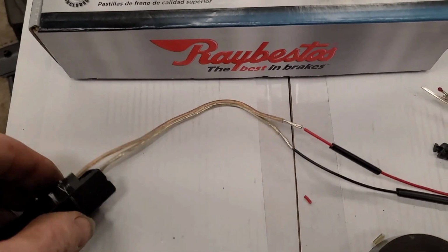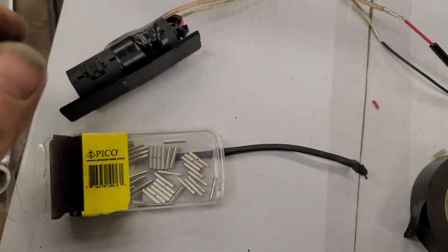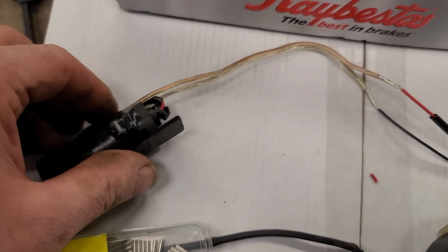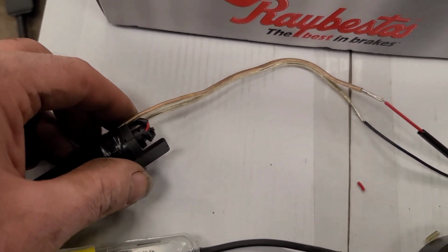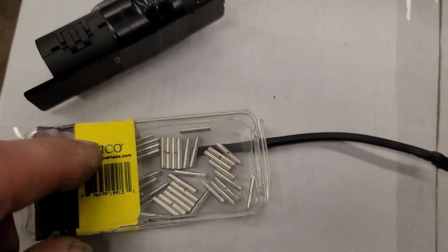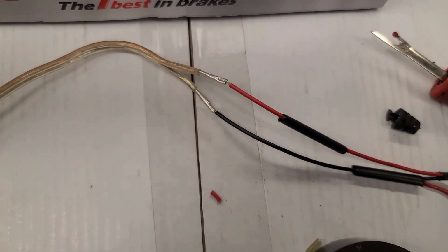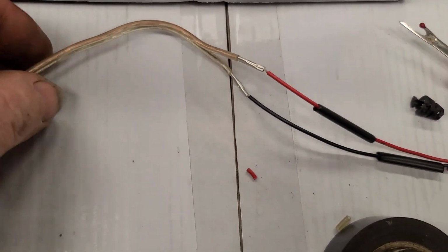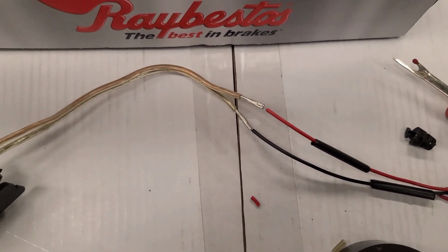So I decided I had nothing to really lose except a few minutes here to splice some wires. So I managed to cut this off, and I made the splice and folded it up so that it hopefully won't bend there. And I used some speaker wire to attach it in these uninsulated butt sleeves, and a little bit of heat shrink, extend the wires, make the joint somewhere else so that this part of the wire will bend with the seat movement, and we'll put it back together and see if it works.